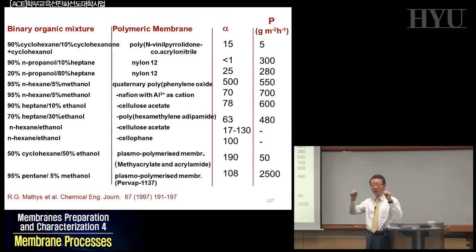A very thin layer of polyvinyl alcohol was cross-linked on top of the polyacrylonitrile PAN-based membrane, and they made flat sheet membranes. This flat sheet membrane was stacked layer by layer, and then pulled in the vacuum. Okay? When they supply the aqueous ethanol containing about 90% of water and about 10% of ethanol.